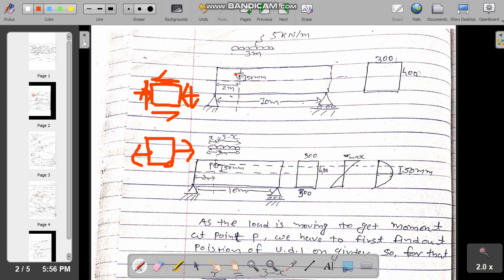Okay, and the shear stress is the same as above. And if we consider the element at the top fiber, whether it is compressive or tensile, as you know, the extreme fiber does not carry any shear stress. Okay, so this is the basics. At the extreme fiber we don't have any shear stress, and we can also see this from the diagram. At the extreme-most fiber, whether it is compressive or tensile, we don't have any shear stress, so it is 0.